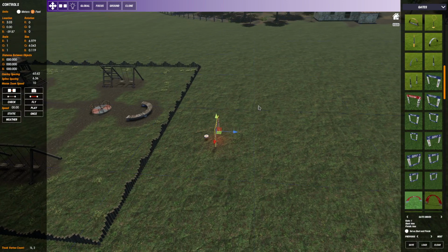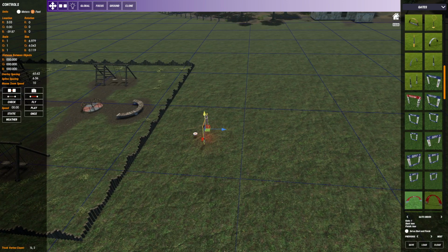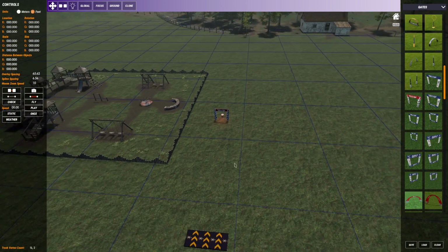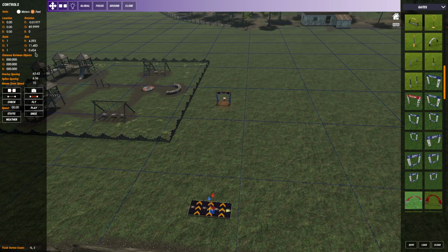So I'm just going to select this and you can see that this green arrow is facing up. I'm going to type 90. And now I can see that the disk is facing away from it. So this is oriented correctly. And to place it, I'm just going to make sure that this is still at 0, 0, 0. Click this, and I can see on the image that this is about at 0 on the red direction and 50 on the green direction. So that's not correct. That was not the right box. So change this back. So 0 and negative 50.